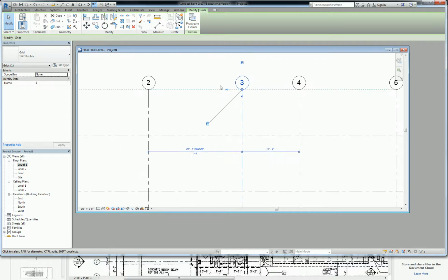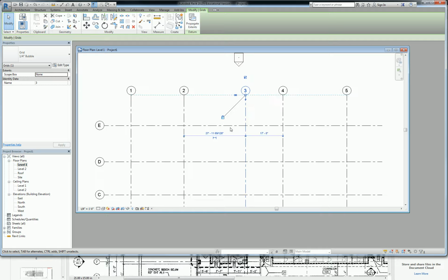So I mentioned that there are a couple of other anatomical things here. They're really, really tiny on this screen, so pay very close attention. There's this 3D button right here. When you hover over it, it says switch to 2D extents. The good thing about these grid lines is that they are a three-dimensional object, even though they're really a planar reference. So the limit of this grid, when this says 3D, is right there. If you cut a section in another view, you won't see that grid.